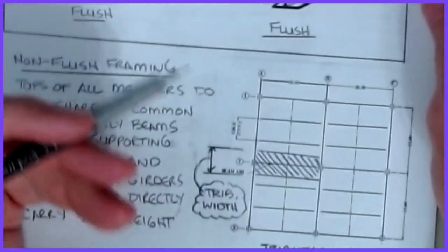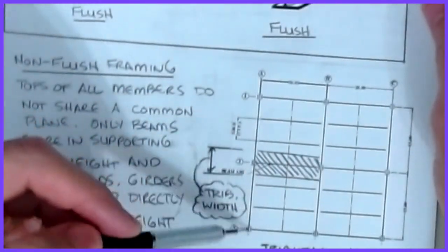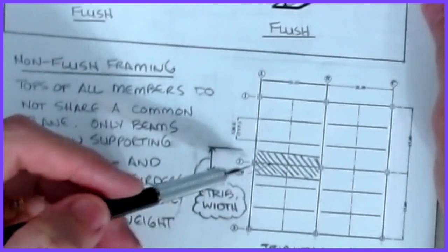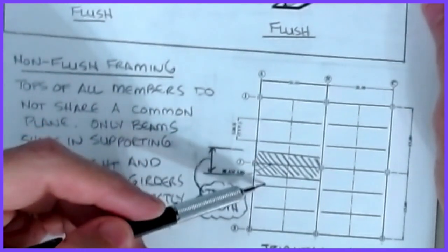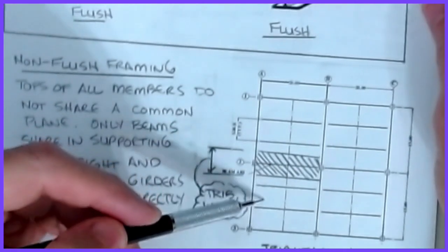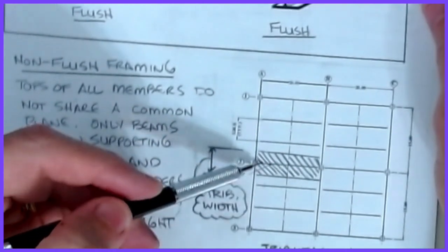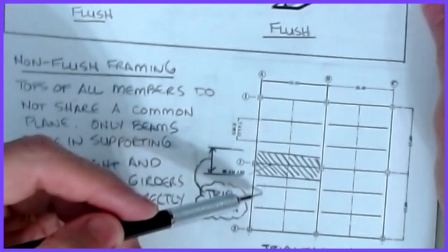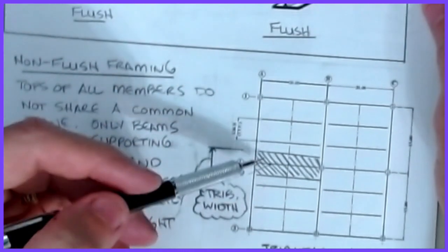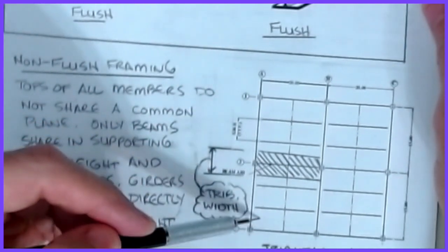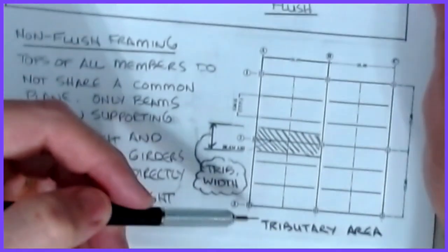Okay. All right. And so if we're looking at the girder that's here, then we can say that this had a tributary width of 5 feet. That's what we saw. Well, if I look at the next guy down, he gets 2.5 here and 2.5 from his neighbor. He's the exact same load diagram as this one. And this one, same thing, 2.5 this way, 2.5 this way. And it's not until I get to that last one that I get something different. This guy out on the end of the building only gets half of what this one gets, because it's only 2.5 feet and he has nothing on the bottom side on those.